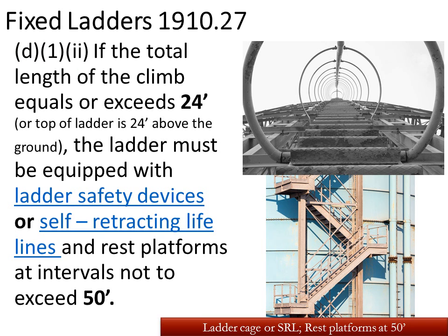If your ladder exceeds 24 feet, so you have a 24-foot climb, you need to have some kind of ladder safety device, such as a cage or a self-retracting lifeline. And if people are climbing multiple sections of 24 feet, so that means I'm climbing as tall as 50 feet, I need to have a rest platform at every 50 feet so people can step off and take a break, both so your hands from gripping can take a break as well as your feet from climbing, if you're on a ladder versus a set of stairs.